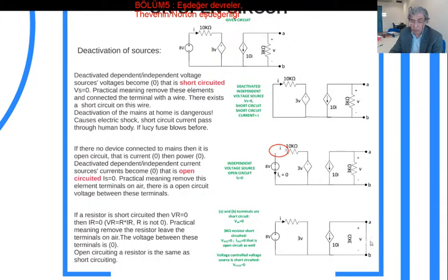You put a wire between the terminals A and B, you remove this resistor, and then you have short circuited this dependent voltage source, because the voltage of this element became zero due to the short circuit of A and B. So there are many actions happening at the same time if you do one short circuit or open circuit somewhere in your circuit. So you have to pay attention if this happens.